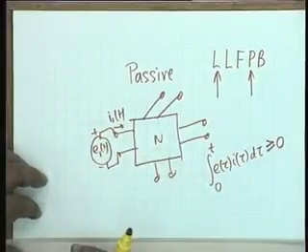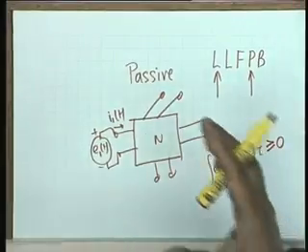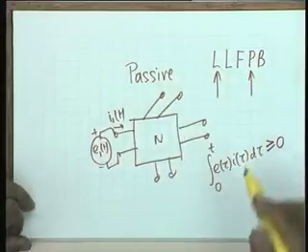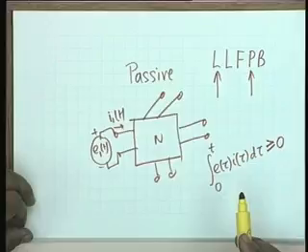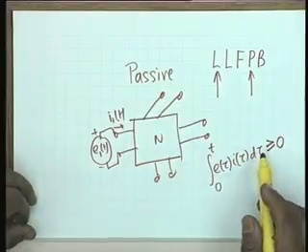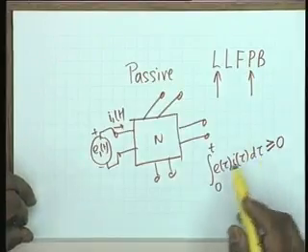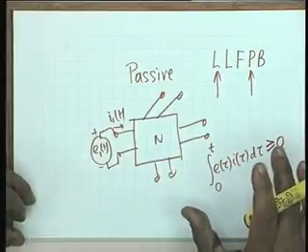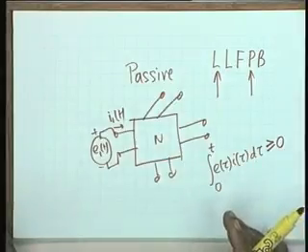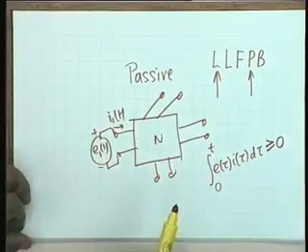It indicates the total energy input to the network. E(tau) I(tau) is power, voltage multiplied by current, multiplied by d tau is the element of energy, and if we integrate from 0 to t, it is the total energy supplied to the network by external sources in time t.